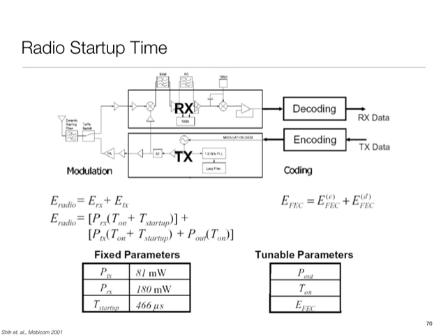And again, these were things which early generation protocols didn't pay attention to. Like I mentioned last time, first generation Bluetooth, the so-called classical Bluetooth, was not optimized for it. When it initially pairs, it can take many seconds, tens of seconds to do that pairing. Likewise for Wi-Fi. But then as these things began to come into play, there were protocol enhancements made, and also Bluetooth Low Energy, for example, is optimized for very rapid syncing, or essentially no syncing. They basically use some advertisement packets to send things out, but these are protocols designed so that that part of the overhead is minimized, somewhat akin to optimizations that took place on the operating system side to reduce the time for a cold start, a wake up that is happening. So we see that kind of stuff.